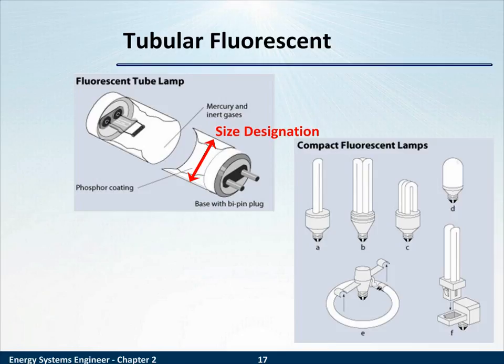Fluorescent lamps work, remember our conversation about how all lamps create light, by ionizing a gas, which then excites electrons in a mercury atom. The complexity here is that in a fluorescent lamp, when that electron relaxes and emits a photon of light, that photon is in the ultraviolet wavelength.